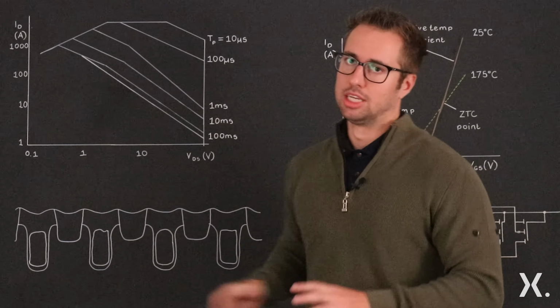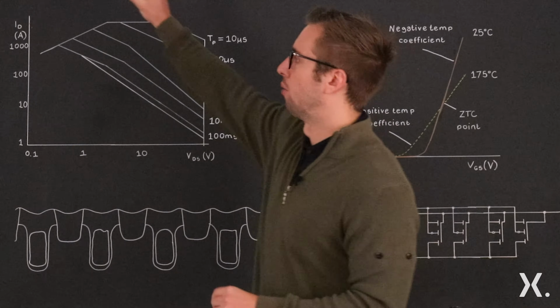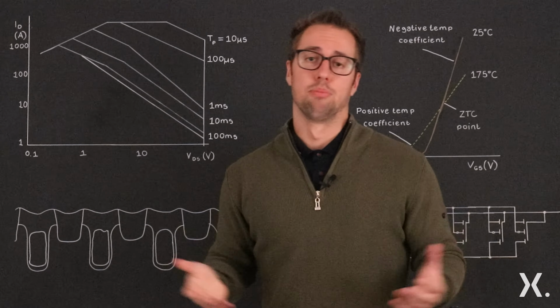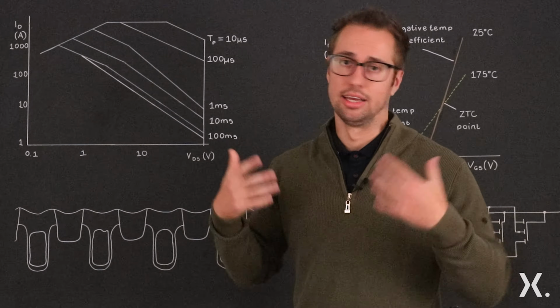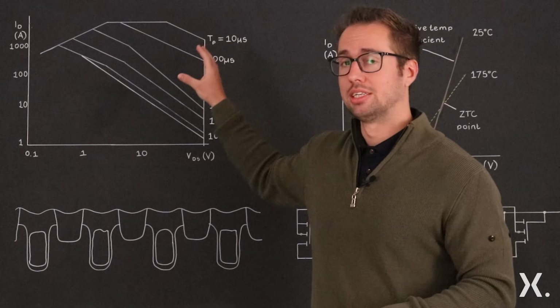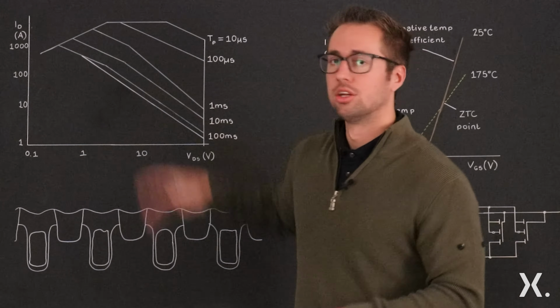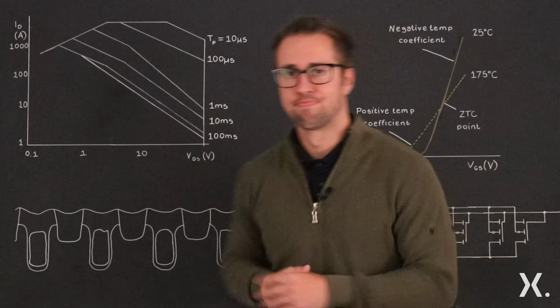Why this is important is because in a datasheet you'll often see a power rating. So all Nexperia Power MOSFETs will have a power rating. However, that power rating is steady state and doesn't apply to a MOSFET in linear mode.